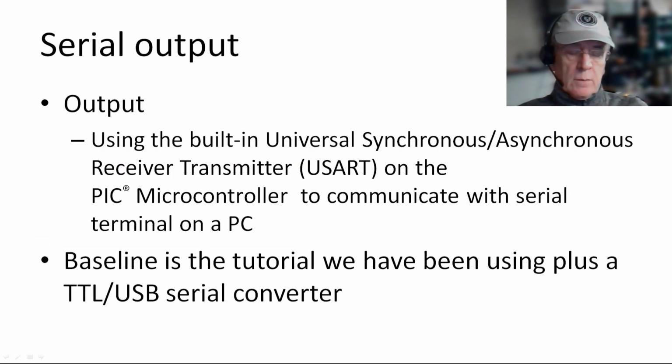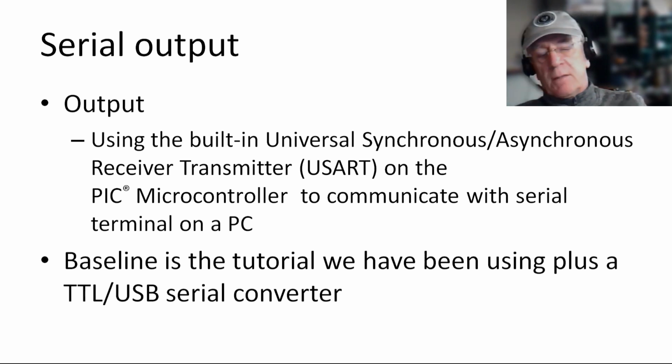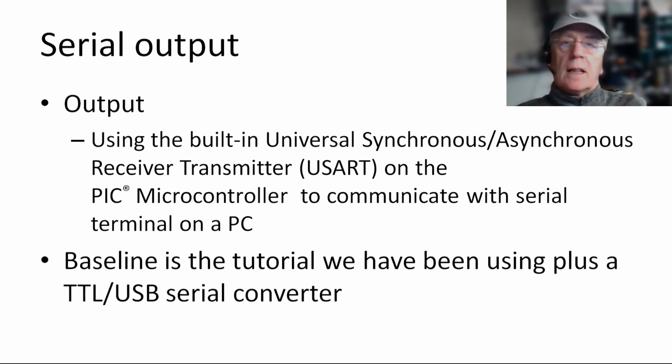So let's have a quick look and recap what serial output is. You're going to be using the built-in UART, or universal synchronous asynchronous receiver and transmitter, that's built into the PIC. And it will communicate over the serial communications line to a terminal on a personal computer or PC. The baseline for this tutorial is everything we've done before, plus a little connector that we'll have a look at in a moment.